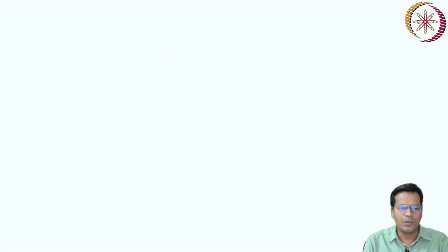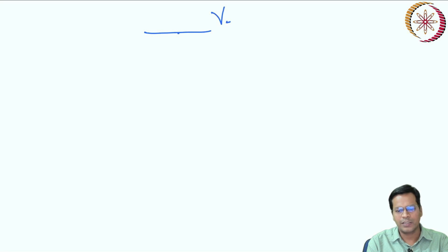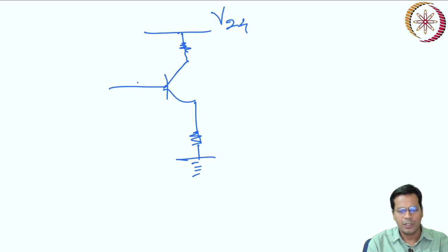So if you remember, you can do switching using a transistor. Let us say this is your high line where you have a voltage of, let's say, 24 volt, if your motor is 24 volt. This is your transistor. You must have some sort of small resistance to bias the transistor, and this is your input. Okay, so your motor can be fitted somewhere over here.